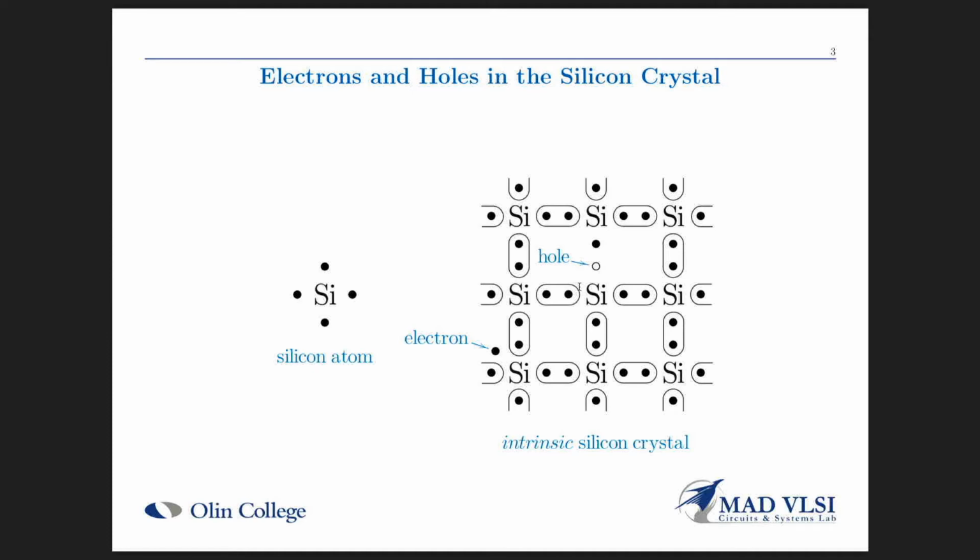charged particle. Because what will happen is that the valence electrons have a tendency to move in an electric field in the same direction as, let's say, the conduction electron would. And so you'd have a tendency to want to fill that hole from over here, and so the hole is moving in the opposite direction. And so that would be behaving like a positively charged carrier. And so for bookkeeping purposes, we do consider holes to actually be a positively charged particle that is moving under, let's say, an electric field or something like that.